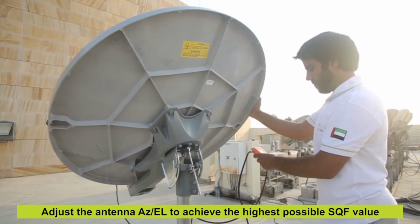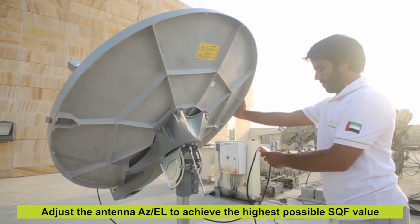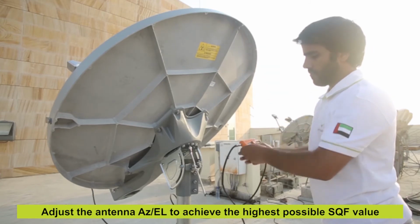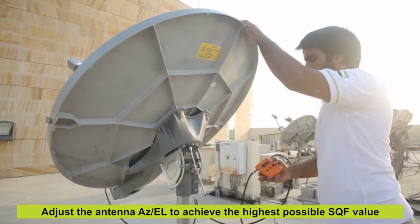It is advisable to set the elevation angle as displayed in the modem page and start sweeping within the azimuth range. The elevation angle is to be adjusted if no signal was received.